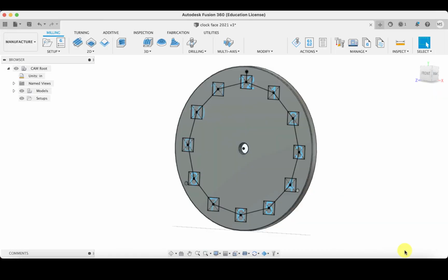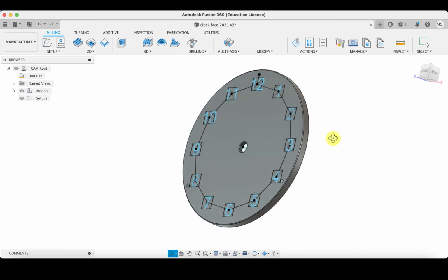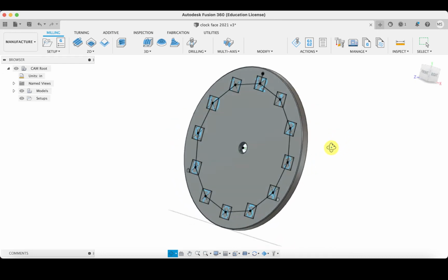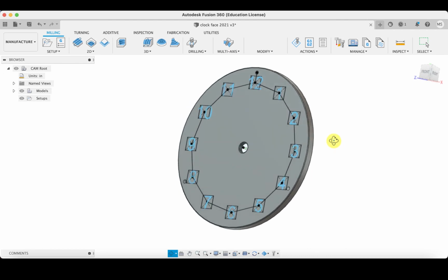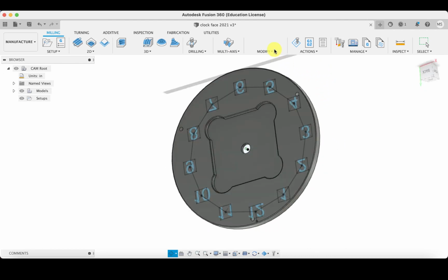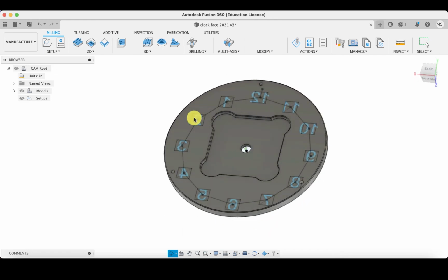So I'm going to click close. Now we're back looking at the clock face. The clock face is made of aluminum, cut out of a piece of aluminum that's about 6 inches by 6 inches by 1/4 of an inch thick. The first thing we do with our clock face is to drill this hole and mill out this pocket in the back. That pocket and hole provide a place for the clockworks to attach and rest, but for milling, this pocket in the back